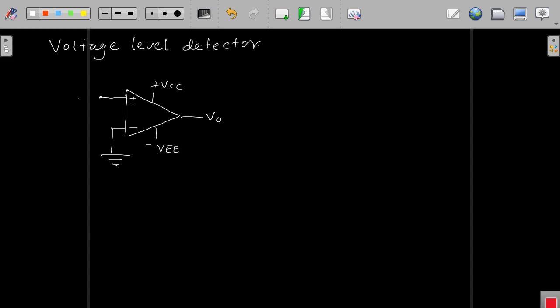So what I would do here is, I take VCC here, and this is plus VCC. Let me call this R1 and R2. So this is my VR2 now. This is VR2, right? So whenever your input crosses VR2, you get the switching. Earlier we had seen when the input crosses 0, or very strictly speaking 300 microvolts in that particular example, right? Then the output swing we are going to get, but here this VR2 is my reference now.